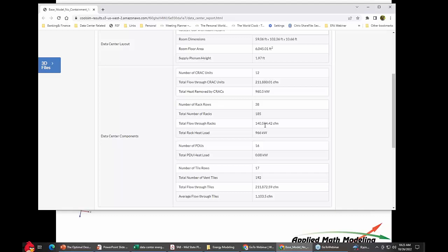You can set the delta T if you like. We use 30 today as an average. You can use whatever you like, 25, 20, it's up to you. For older designs, if it's older equipment, it's closer to 20. If it's newer equipment, it's closer to 30. 25, I think, is the default in CoolSim. We keep increasing it because the heat exchange is getting better on these devices. The total load in the room is 966.